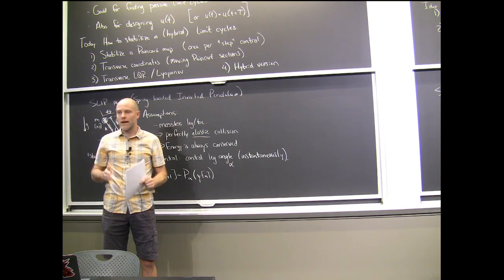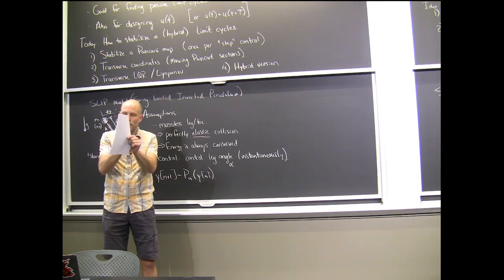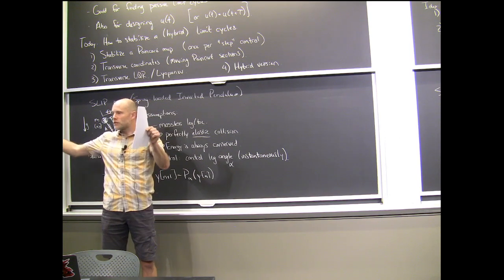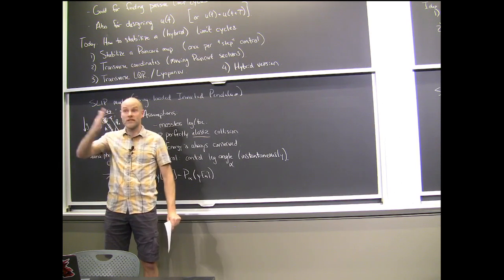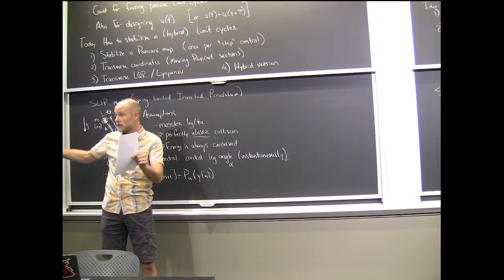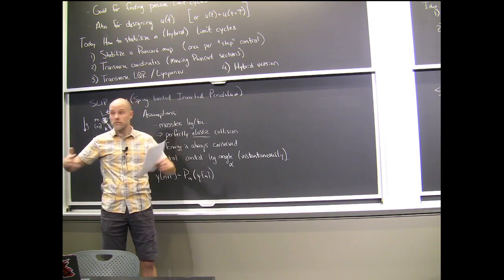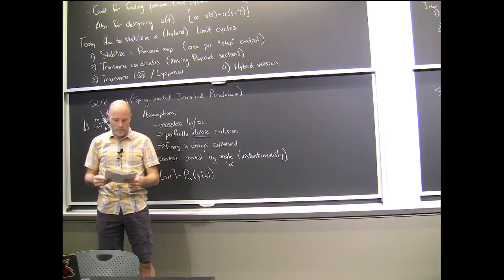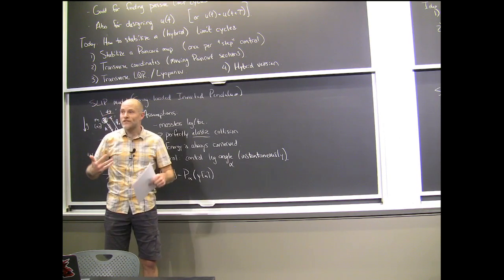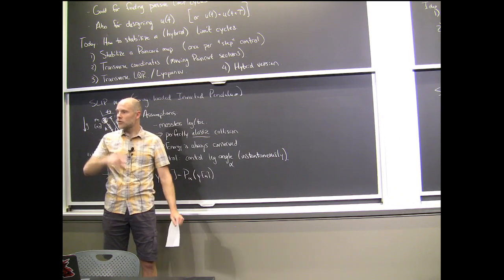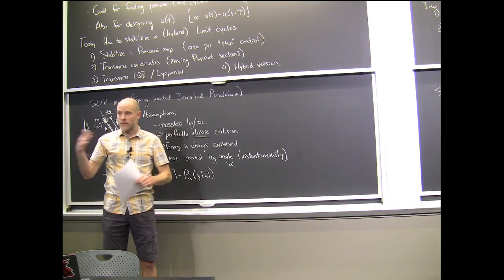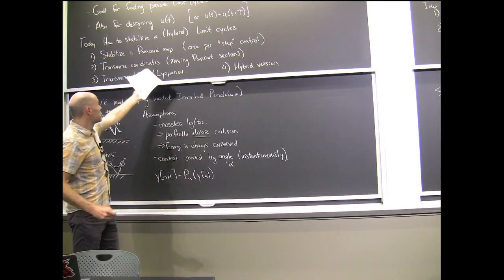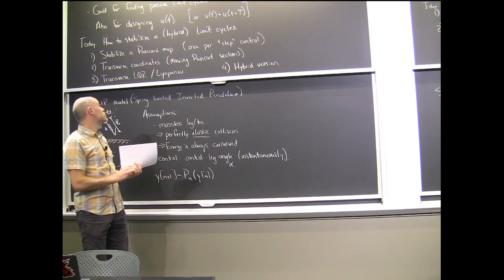You're setting up a discrete map. Or even if you had maps in a mode sequence, going from impact 1 to impact 2 to impact 3, I could still design, let's say, a time-abstracted, varying linear dynamical system and do LQR on the once per event control decisions. And that can be very powerful. But of course, you can do better if you're willing to make control decisions throughout the cycle. So let's think about how to bring our tools over to that. And the first thing to do there is to give you this idea for limit cycles of doing transverse coordinates.